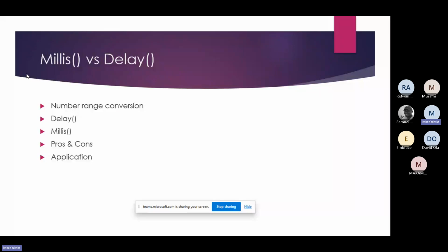And once you want a shorter delay, that is when you call delay microseconds. That means it is a very short delay. We use that once we want to use a pulse. We need the pulse from that microsecond delay, for example, in our ultrasonic sensor.